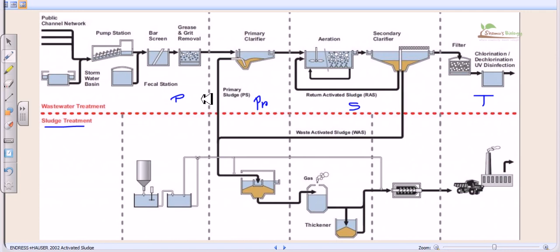Now in the preliminary treatment, only the mechanical treatment is being done, and in many wastewater treatment plants the primary and preliminary treatment are fused together, and they call it the primary treatment. Now in this primary treatment, basically the physical apparatus are used to mechanically separate particles from the water, because the water which we collect contains solid as well as liquid parts. Now the liquid part also has nutrient sources, because this wastewater contains human waste. That means we have protein products, carbohydrate or sugar products and all these things in it, and also the fatty acid products.